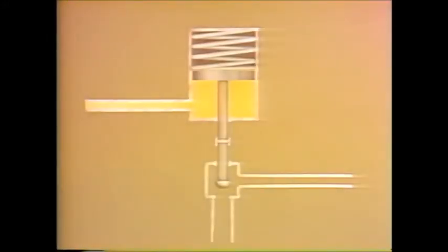In the electro-hydraulic control system, the mechanical governor is replaced by an electronic governor. The governor sends a signal to the control system. This signal indicates the turbine speed and is used to regulate the control valves. A second governor is usually installed to function at abnormally high speeds and operate the intercept valves. In effect, the governors control the flow of oil under the hydraulic actuators for either the control valves or the intercept valves. For now, we'll just consider the operation of the control valves.